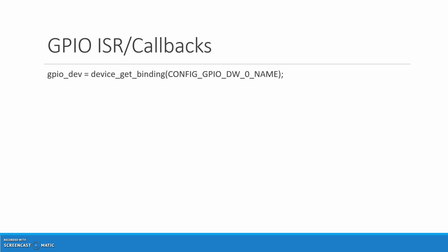The module or device is connected to multiple boards and multiple pin chips, so the first thing we should do is detect which device we're going to work on. The device is picked using device get binding. It retrieves the device for which the subsequent actions are to be performed. Suppose we have picked a chip, then on this chip we will have multiple GPIO pins.